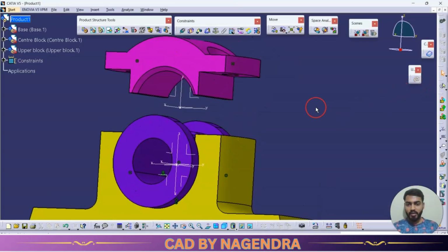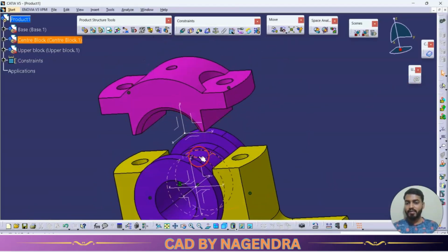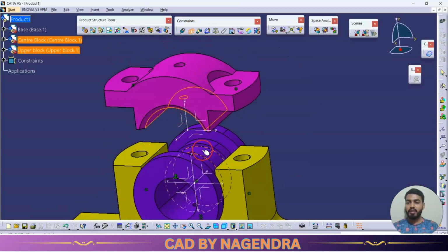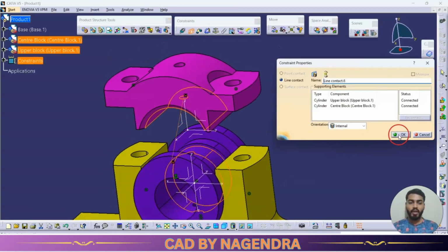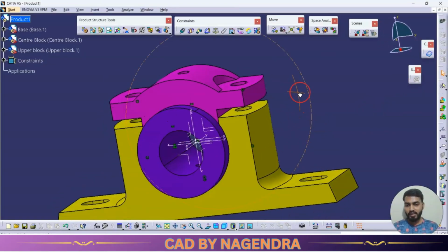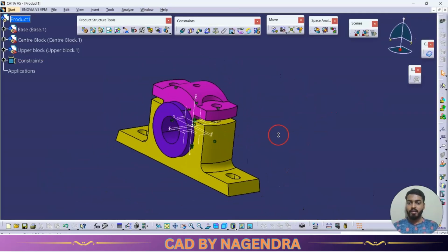just if we make update, it will come straight. Here, the cylindrical face should attach with the cylinder. So here we are dealing with surface to surface. In such condition, we can go for contact constraint between the cylinder profile to the cylinder profile. Okay, let's update that. Properly, it will fix there like this.